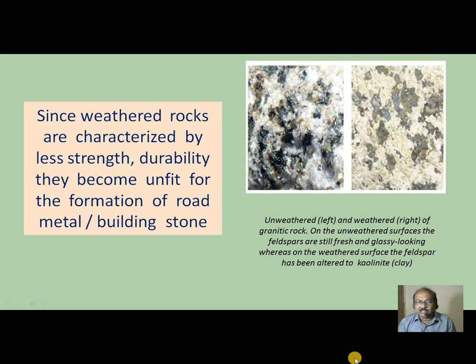Usually, weathered rocks are characterized by less compressive strength, and the durability also is less. That is the reason they are unfit for the formation of road metal or a building stone. If we see the picture, the left part is unweathered granite, that means it's a fresh rock, and the right side is also a granitic rock, but it is totally weathered.